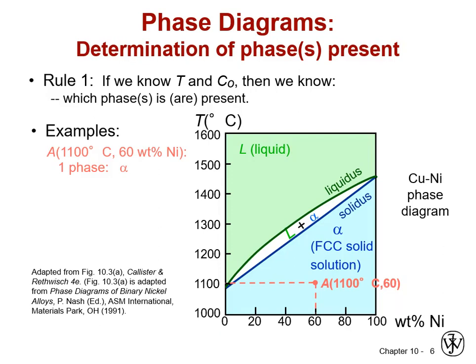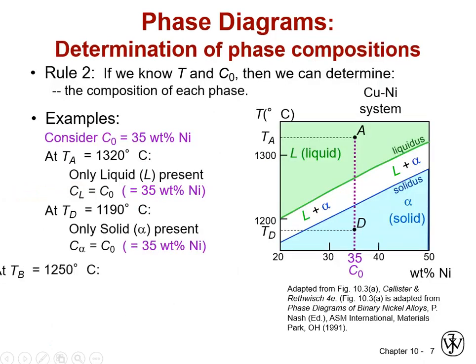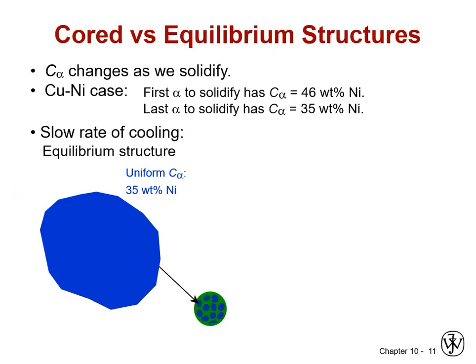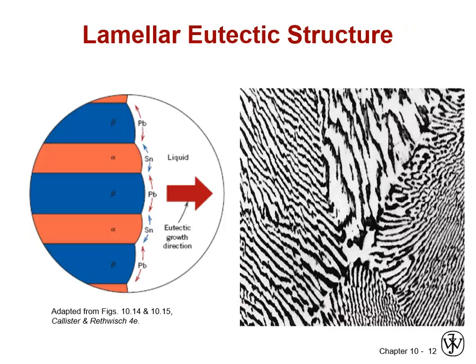And so if you were planning a thermomechanical process close to what you thought was the melting point, you might actually be performing it above the melting point, and you could suddenly have something splattering with liquid metal in a forging process where you hadn't expected it, and that could be a severe plant safety problem. That used to happen in the early days of steel making and was referred to as a hot short, and was very dangerous in a foundry setting or a hot working setting. So understanding that with respect to processing is very important.